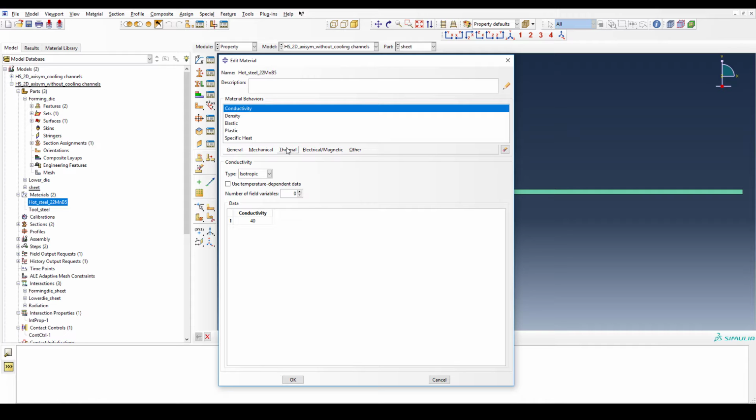In this case, you guys can definitely check it out, you won't see a big difference if you activate the heat generation, especially given the fairly slow process speed. At 2 seconds, it gives the heat a lot of time to dissipate into the dies. So whatever heat is generated, you would barely notice because the dies will take it in and extract it from your sheet.